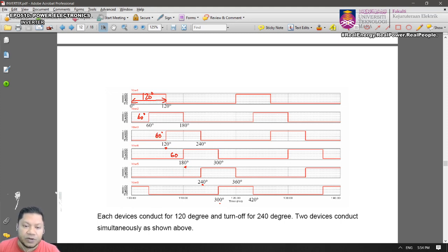So S1, S2, S3, S4, S5, S6, and this is very important, as well as the labeling of your switches just now. So it is always S1, S3, S5, S2, S4, S6. If you wrongly label the switches here, you will not receive the correct output voltage. Right. Okay, so let's look at the circuit operations, and let's imagine that we are at this particular point here.